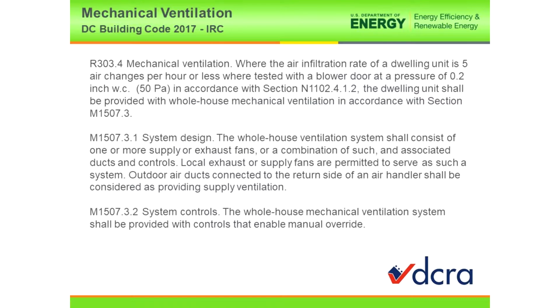Well, back in 2012, sometimes when enforcing the code, if we gave it to you all at one time, believe me, you guys would probably have a fit. It would be some drastic changes you would have to do. So we didn't exactly enforce it, but if you put it there, then we were happy with it. But now, because we're at these 3 air changes, which is a whole lot lower, you guys are going to have to show us how you are mechanically ventilating the dwelling.